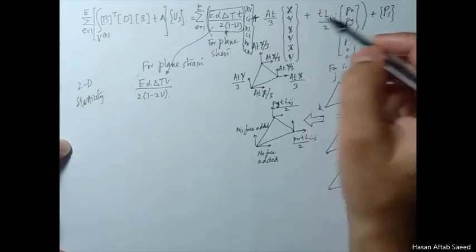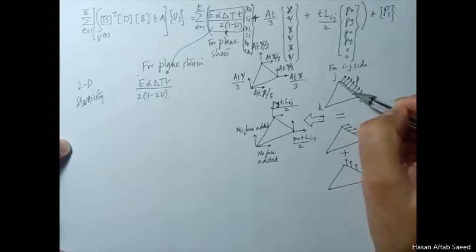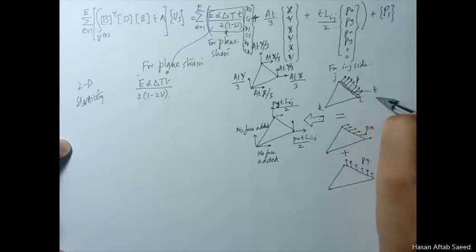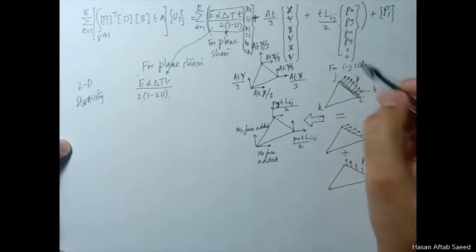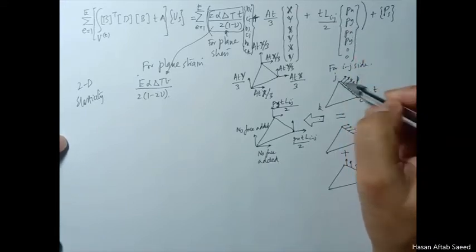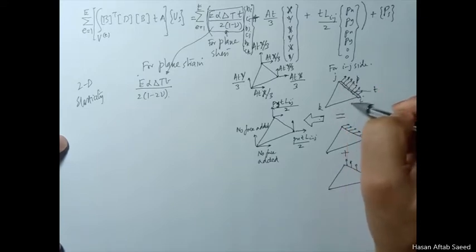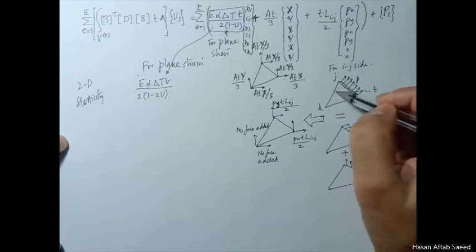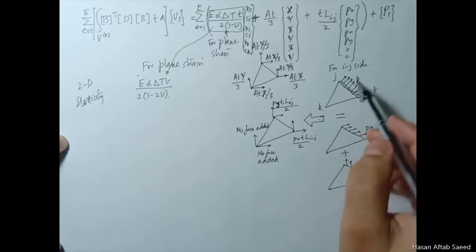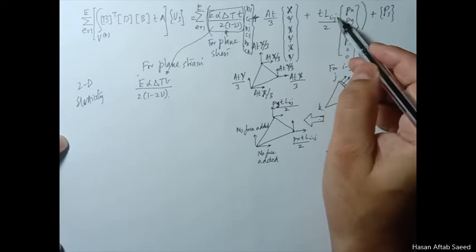This t is the thickness of the element, and this L_ij shows that it's the length ij that we are talking about, not length jk or ki, because no pressure is on these faces. So you multiply this pressure force with the area, you get something in Newton.